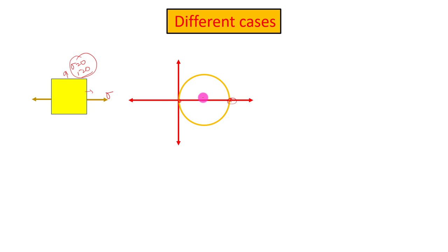Now if we connect these two points and take the midpoint of the line generated, we get the center of the Mohr circle, and the circle is going to look something like this. For this case, the circle will pass through the origin, and it completely lies in the first and fourth quadrant.